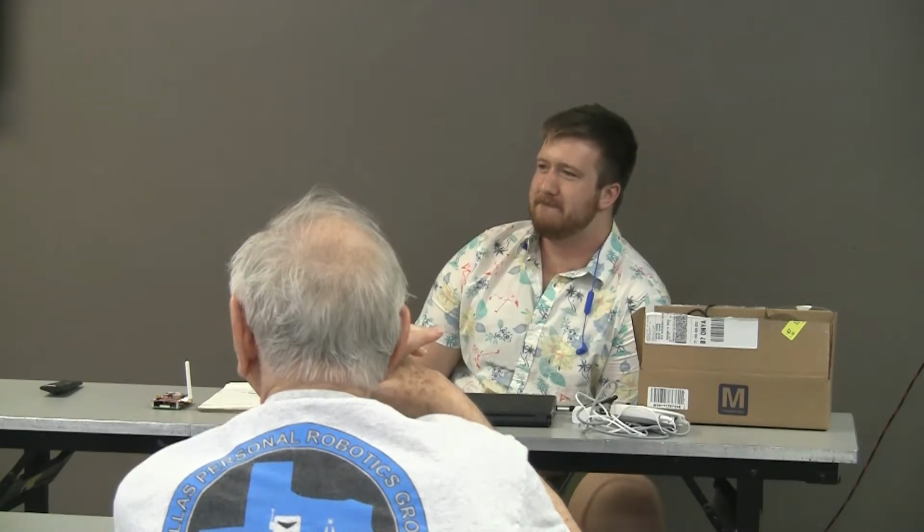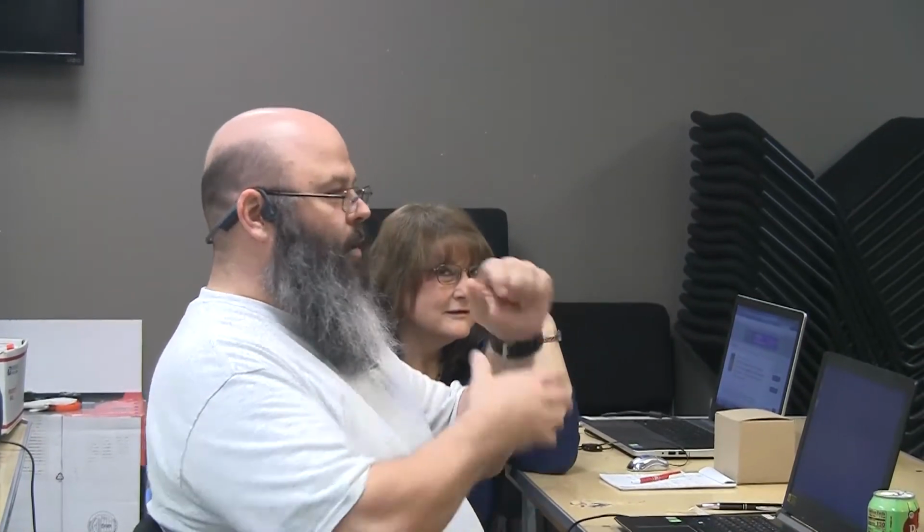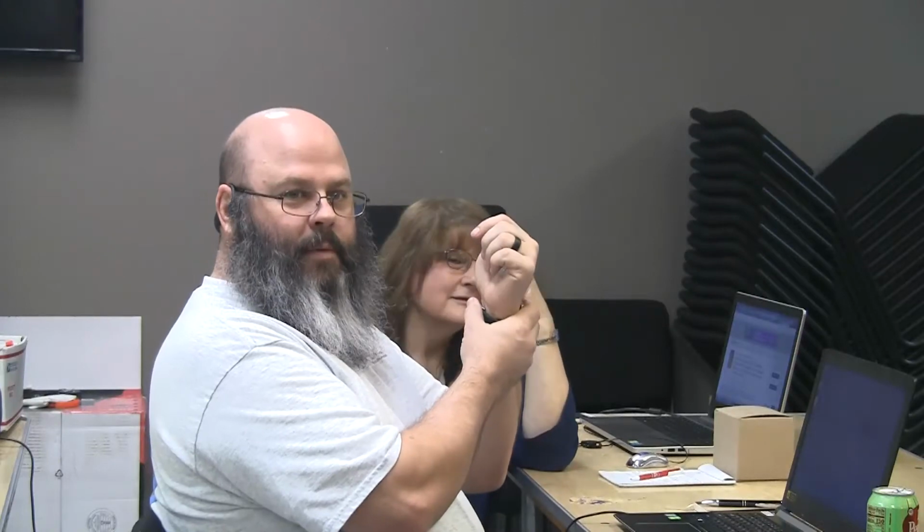I've got a case that I looked at, if y'all want to hear real quick. Think of it as something I tried as a paper napkin design quite a while back with the Zigbee chips. Based on how Zigbee works and the fact that it can transmit an RSSI, you can get about 10 centimeter resolution from it. The concept was you could have a wristband with a Zigbee node, and on one Zigbee network you can have 65,000-ish endpoints. So you could literally flood an area with receivers.